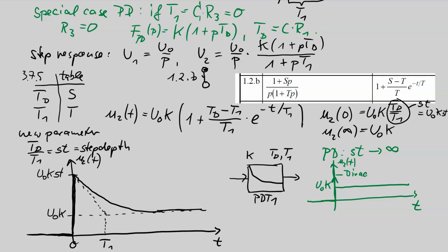But you see, again, if the step response carries a Dirac impulse, we have to be careful in simulations or in calculations and predictions with mathematical equations. If the input of the circuit jumps like a step function, the output had theoretically a Dirac impulse.